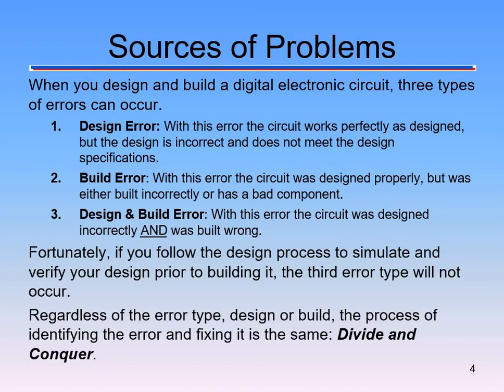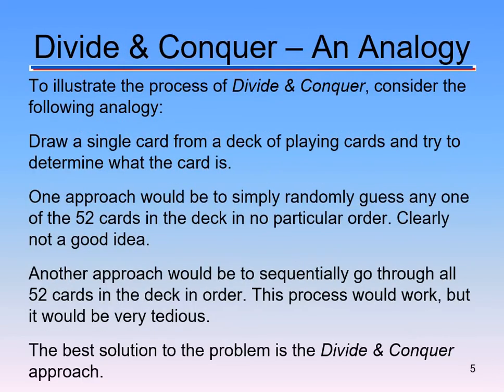A couple different processes of working your way back through your circuit. One is when you actually wire it up, marking things off as you go so you know what you have and haven't done and where they're located on your breadboard. All right, but a very, very common one, main process that we're going to apply is called the divide and conquer process for solving the problem. So we're going to divide and conquer. So instead of trying to tackle the big picture, we're going to make it into small pieces that kind of make sense as we go and break it down step by step.